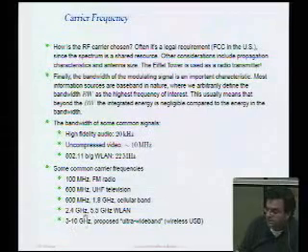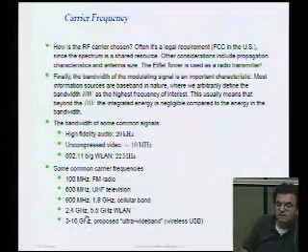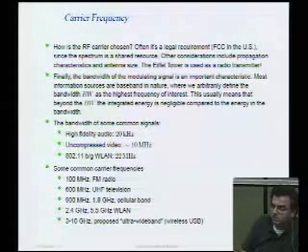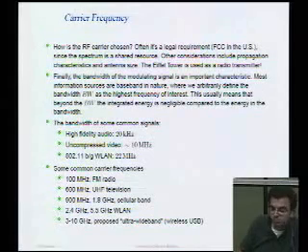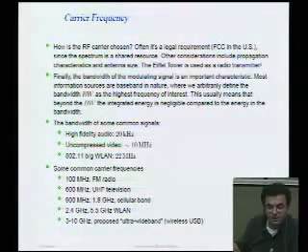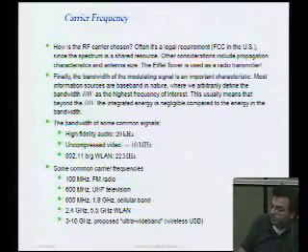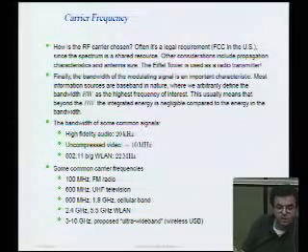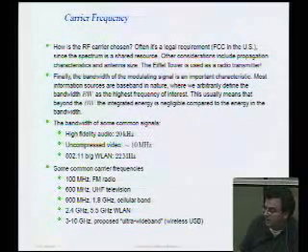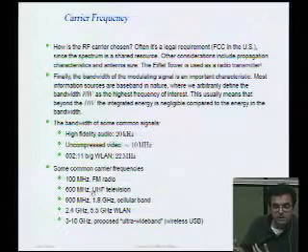And these days, there's a whole flurry of activity in using spectrum in different ways, mostly for data applications. For instance, 3 to 10 gigahertz has been proposed as the ultra-wideband. Ultra-wideband because it's so much bandwidth. It's 7 gigahertz of bandwidth. Don't get too excited, though, because the amount of power you can transmit in that bandwidth is only about a milliwatt. But people envision this as a very short-range, high-speed link. Let's say like your USB cable without the cable, or wireless USB. So there's lots of spectrum out there, and it's being used in new ways.